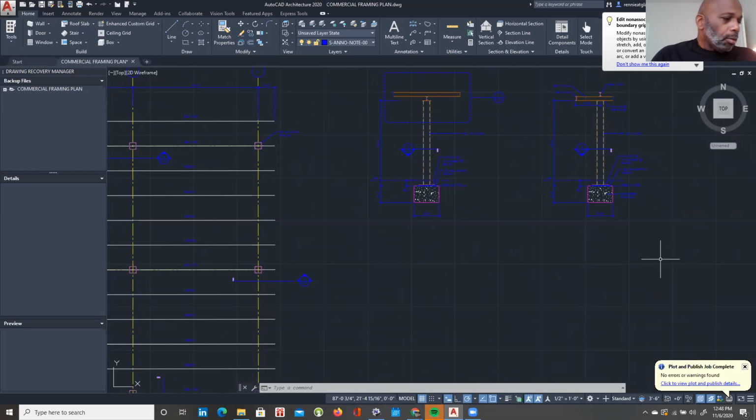Well, as we look at the sample drawing, you're going to have to draw in model space, as a separate drawing, the plan detail 2 and the section C. However, detail 1 is the same section as the top of section A. That's not a separate drawing. When you annotate it, however, you're going to have to change your annotation scale to 1.5 inches and then add those dimensions and those notes.